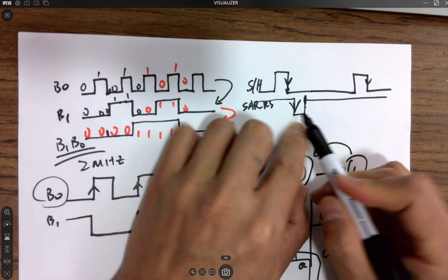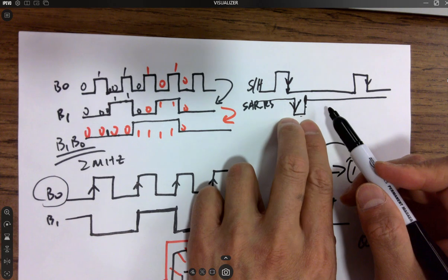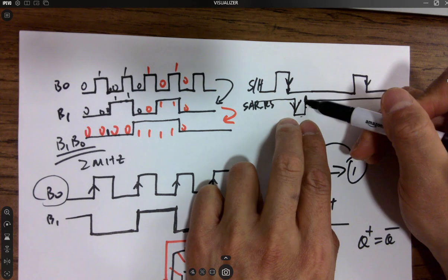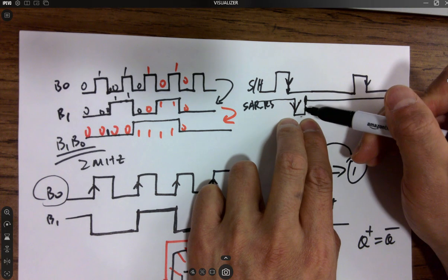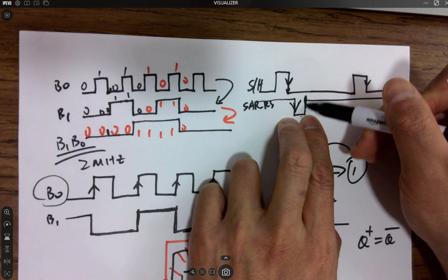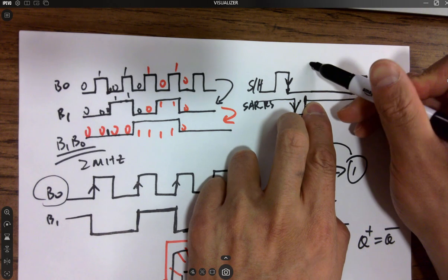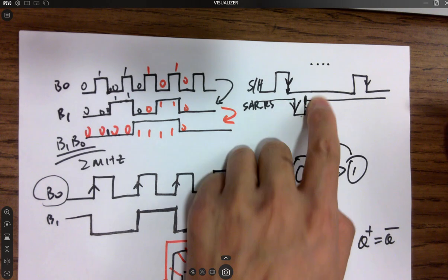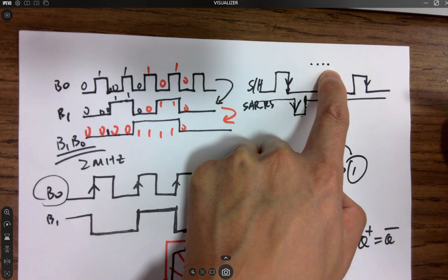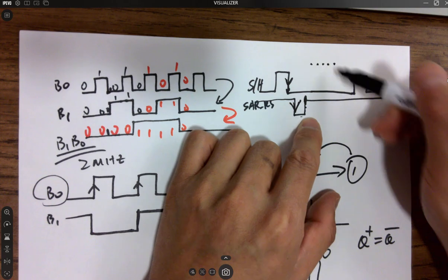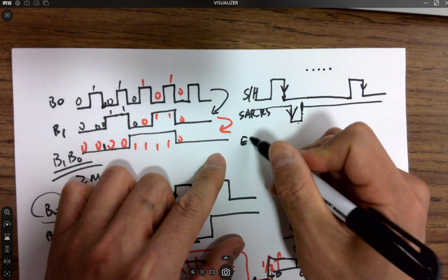So you can make this shorter if you want. I didn't, but you can, right? You can make this shorter by designing a fancy circuit. But I would just wait for another rising edge to put it back, right? And then you can do the A3, A2, A1, A0 register at the rising edge of the clocks, okay? And then once that is ready, you need another clock to do your end of conversion.